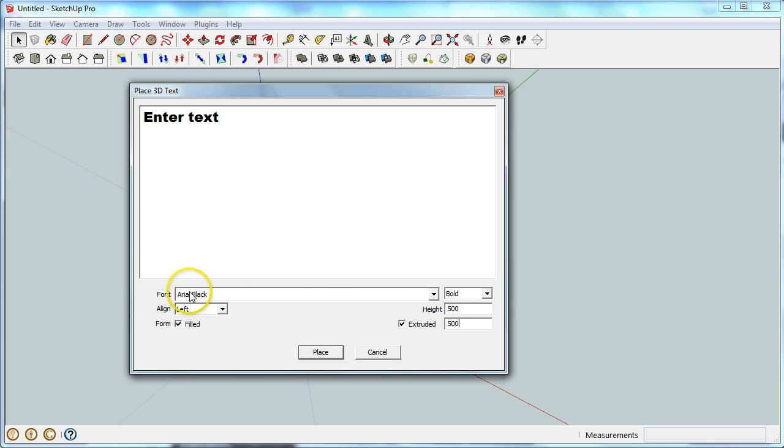I like to use a bold font like Arial Black. I want to make sure it's as bold as possible. I also like to use capital letters, because if I use anything spindlier than that, the plastic is not actually where the letters are, it just doesn't use enough plastic, and the objects just become very easy to break. So I'm going to use all caps.